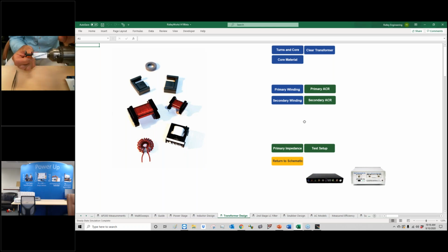And as I go, I've been doing this for quite a while, so I'm quite good at this. I'm not as good as the professionals, of course, but you're trying to get the windings so they're all touching each other, but they don't overlap. You don't want to crisscross windings because that creates bulges in your transformer. So you have a little gap there. Push the gap down.